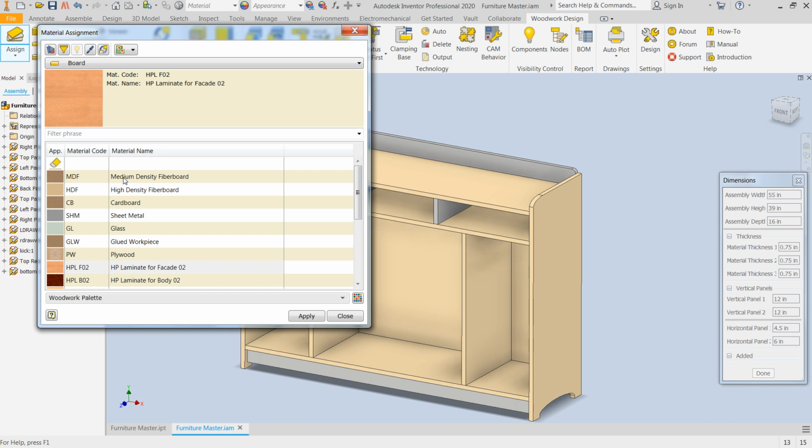All of this is adjustable so that your cut list will actually present back to you correctly with exactly the name of whatever the materials are you're using. So even though it is set up out of the box with predefined information, that could either be deleted or renamed to meet your particular requirements. And in fact, you can change the coloration, the grain direction, and everything else so that you can standardize the way everybody works. And that's one of the benefits of using these kinds of tools.